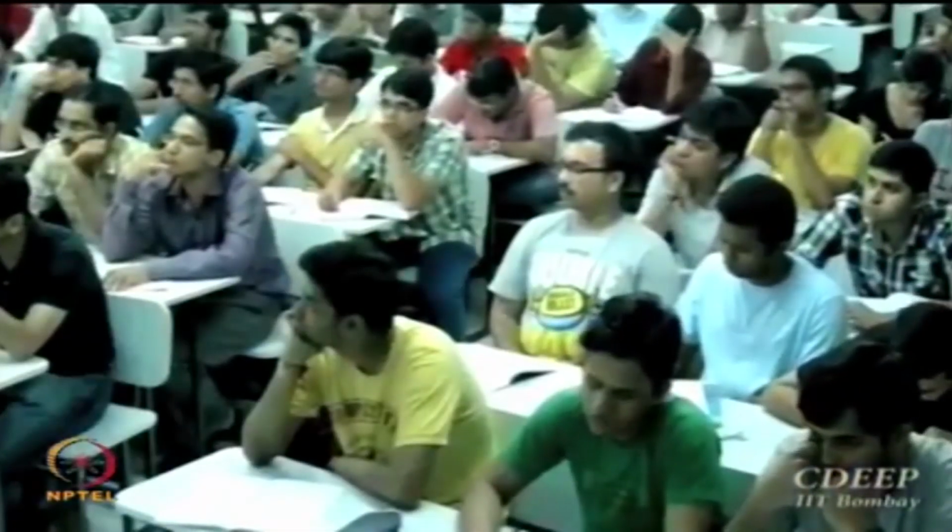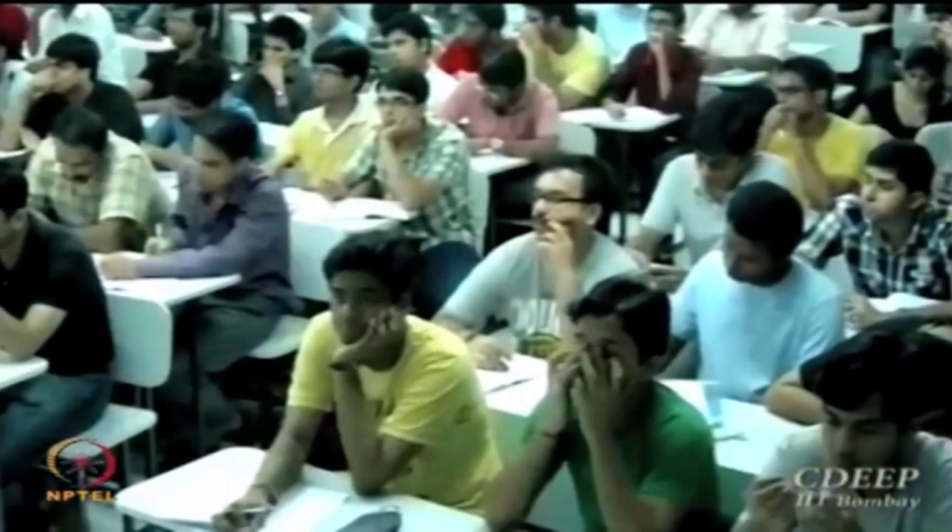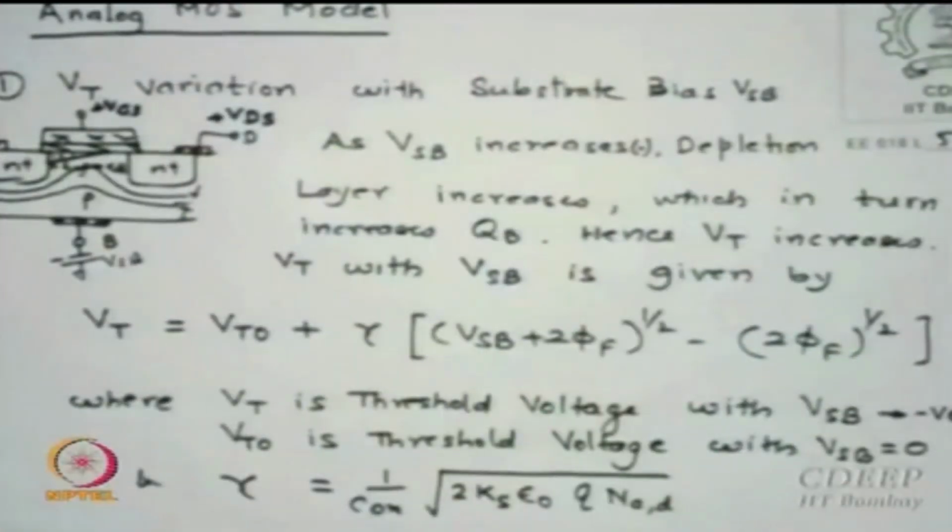In digital CMOS this is the general criterion, because of the swing to be equal we always put VTN equal to VTP in digital, but in analog that is not a compulsion and many times I will not do that. So in which case my two devices will have different doping so that I can adjust my VTs independently. Is that point clear?